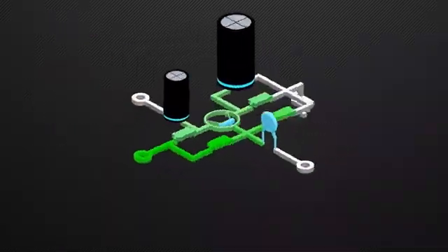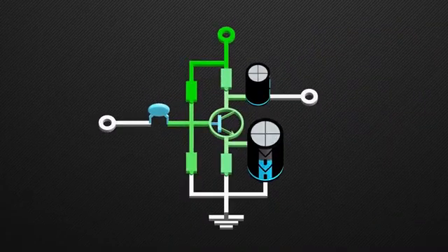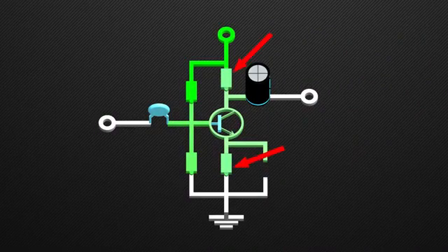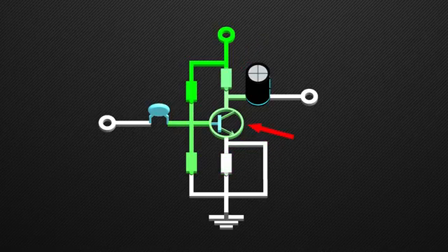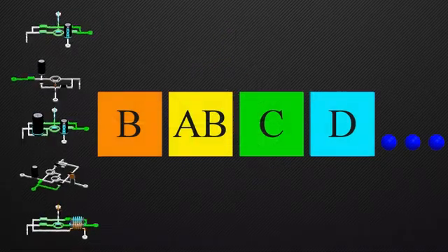This circuit has a capacitor across this resistor. This increases the AC gain of the amplifier. The capacitor will block the DC, thus the amplification of DC will depend on the resistors, but for AC, the capacitor will act as a short circuit. Its gain will depend on the beta of the transistor, which is in hundreds, thus you can amplify a very weak signal to strong signal.